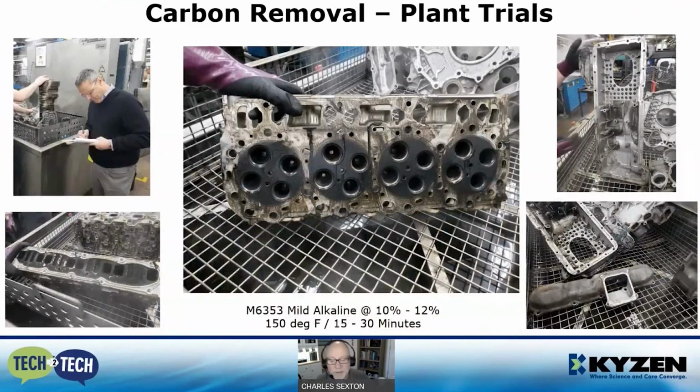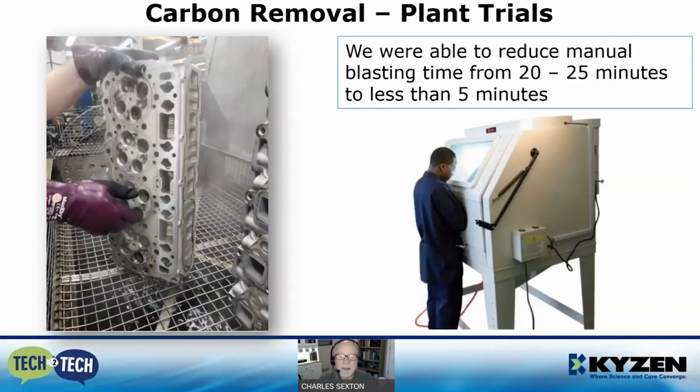Again, this one I'm showing reman because these are some really difficult carbon removal applications. We were able to double the bath life here, and often with carbon, you've got someone or some automated blasting machine that's removing the very, maybe last 5% of the carbon. And in this application, we were able to reduce the time required per engine head from 20 to 25 minutes to less than 5 minutes.